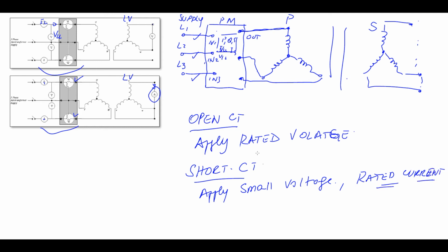Once we perform the open circuit test, be sure before you go to the short circuit test that the auto transformer, because we're going to use an auto transformer at the primary, the line side, just to adjust our input voltage, is brought back. From this test to this test, we bring the knob back to the zero position, 0 volt. Otherwise, we're going to burn the transformer.